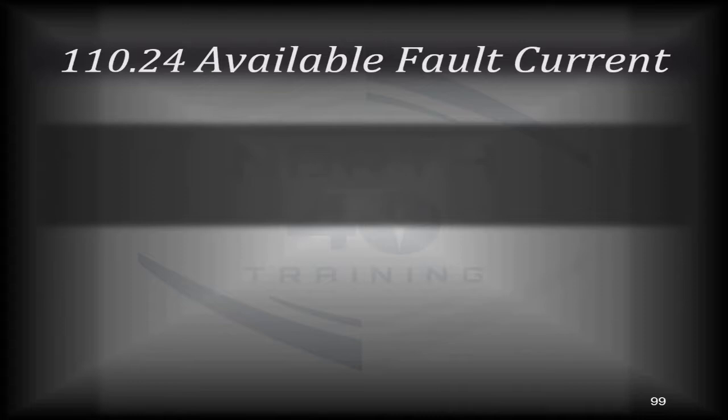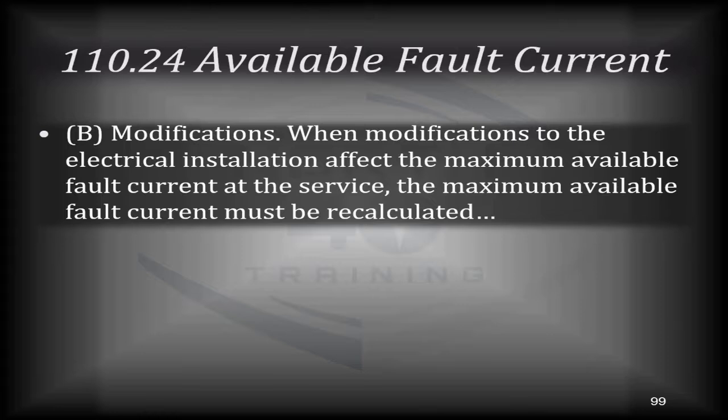110.24(B) says when it comes to modifications, if the modifications could affect the electrical installation's maximum available fault current at the service, it has to be recalculated and relabeled.